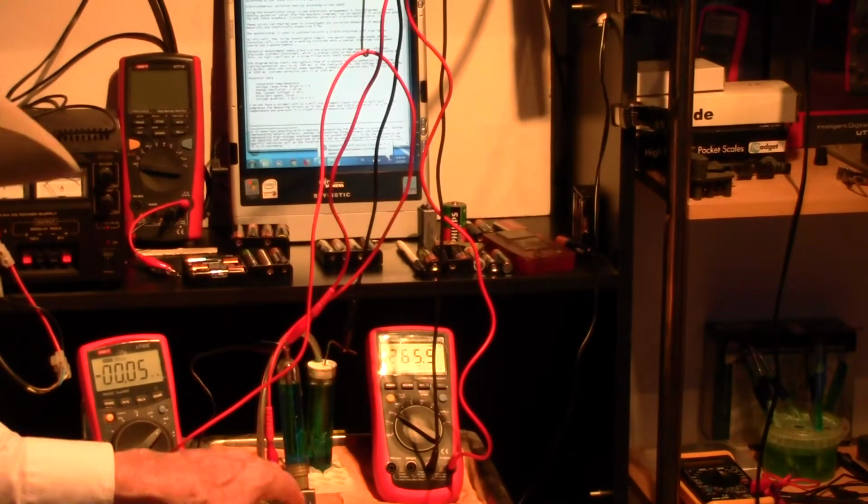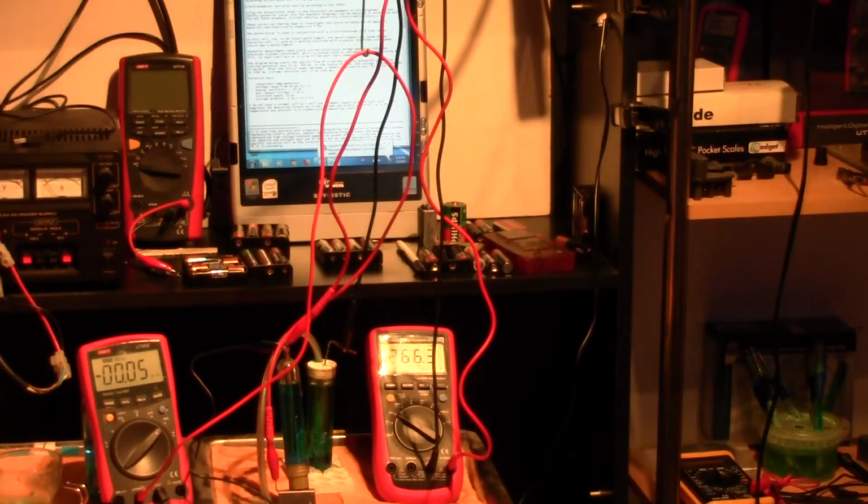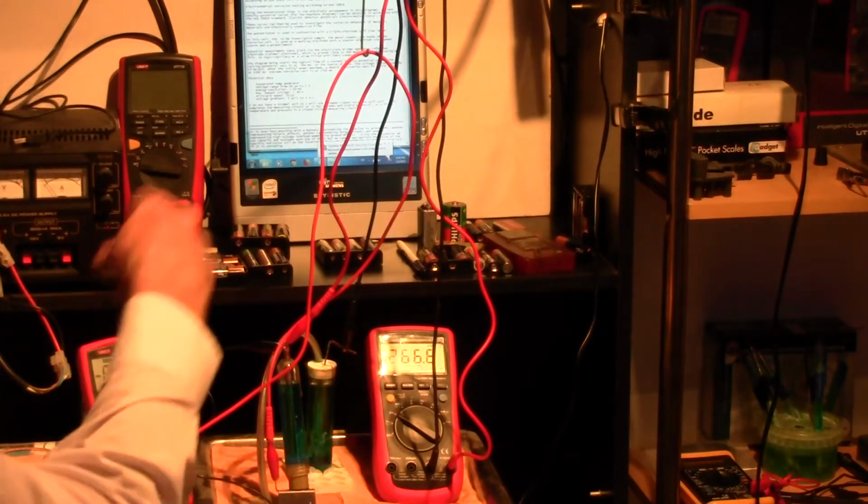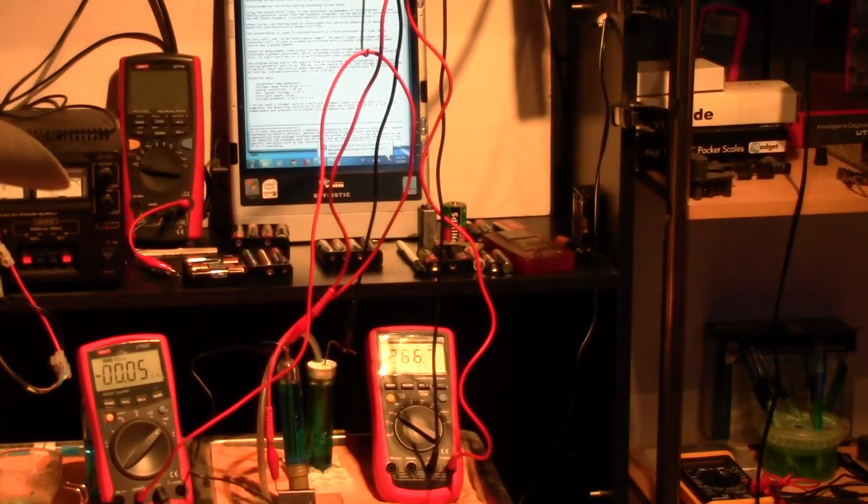Now this is the scientific requirement to actually make measurements of the corrosion reaction of steel or copper or aluminium, whatever you want to measure the corrosion reaction of. This is the way you have to do it. You cannot take that, stick it in the ground and connect the other side to the pipeline and expect that to be a scientific result rendering data that can be sensibly analysed. It cannot be.